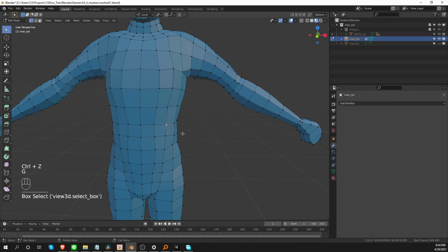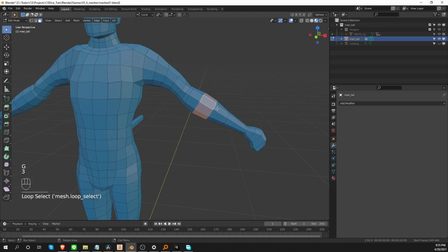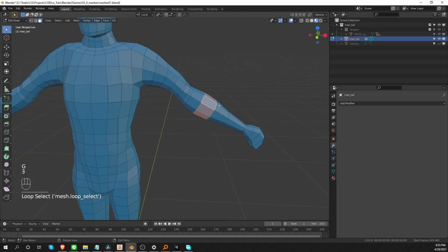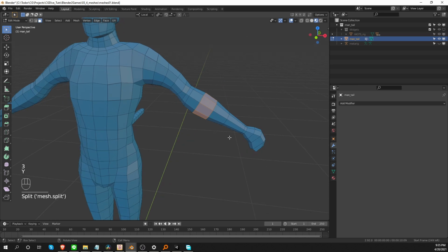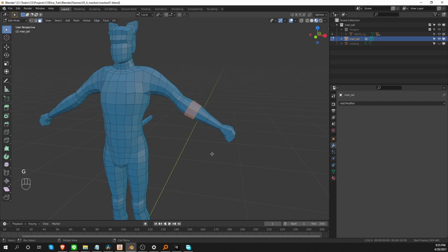And again, if I cancel the movement, it will snap back to its original position, but it is still disconnected. Another one, if I have some polygon selected, if I press Y by accident, for example, at first it may seem like not much happened, but really I disconnected this geometry from the mesh. And now we have a bunch of polygons which are perfectly overlapping with existing geometry, but they are incorrect. They're not perfect geometry.